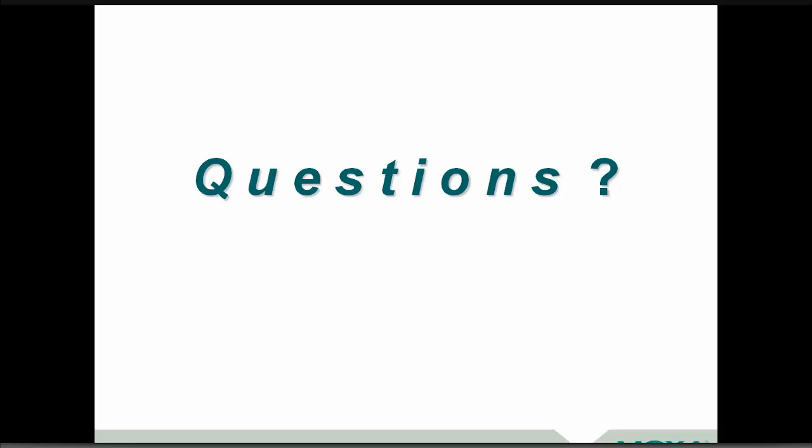Oh, another good question, and we tried to cover as much as we can today, but I think that's really pertinent to a basic understanding of it. And that role is really set on the configuration of the device. In what we've brought to market from Moxa, we've approached this from a couple perspectives. We know sometimes you want to just get something quick and easy up and running, and one way to do that is via dip switch selection, where you can set one device to be the central office or CO, and the other side is set opposite for the CPE. So this is a manual configuration that you have to do on each device separately.